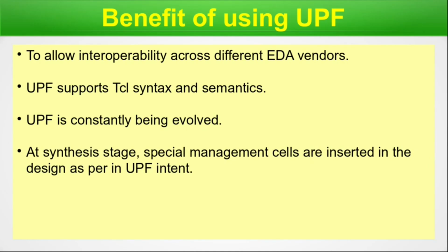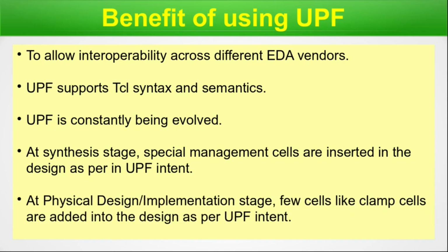At the synthesis stage, special management cells are inserted in the design as per UPF intent. You see that there are a lot of standard cells which are mapped with the UPF application. All those can be inserted at a particular stage of the design. At the physical design or implementation stage, a few cells like clamp cells are added into the design as per the UPF intent. So this is the overall scenario of using UPF.